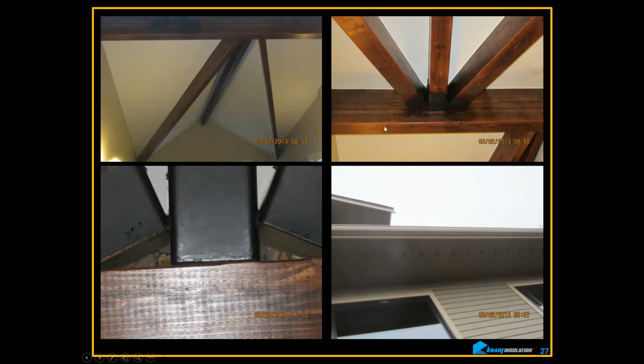And what happens on the connection bracket right up in here is that bottom left, you can see these areas right here. You can see right into the insulation and the plywood. So the drywaller can't get tight enough in here to seal these up. And nobody knew to go back and throw some sealant or something in these tight spaces. So all the air is moving up into this assembly.